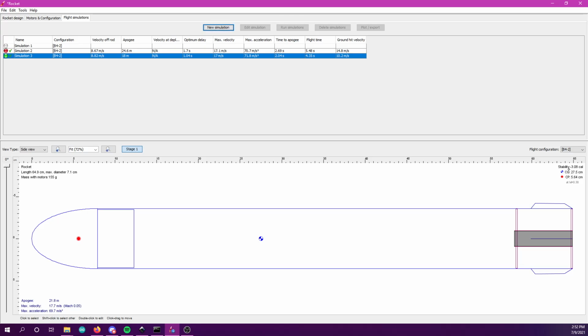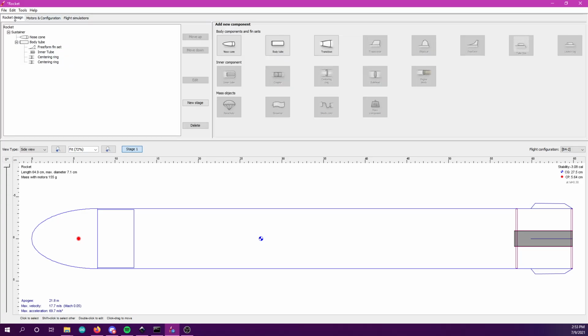The fins aren't big enough to stabilize the rocket. You really want a stability margin around 1.5, 1.7, somewhere around there. And we're not getting that here. We'll talk more about stability margin maybe when the school year starts, because we have a few physical models that we can show you to get a better feel of it. It's a little abstract. Don't worry about it right now.